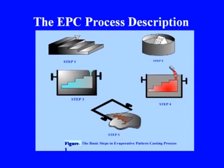In order to ensure uniform and proper compaction, a vibrating table is used for the mold compaction. After completing this process, the cluster is packed in a flask and the mold is set ready for getting poured. A schematic sketch of the EPC process is shown in the figure 1. This is the pattern. The pattern is coated and then finally the pouring is done and the product is obtained.